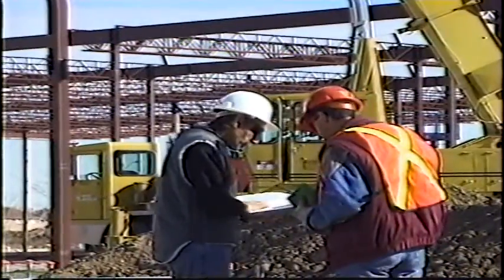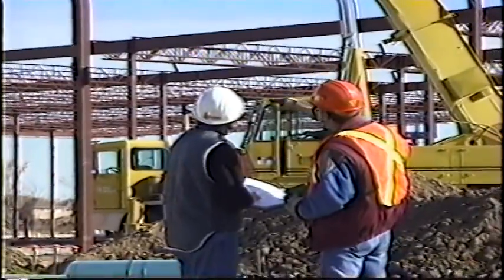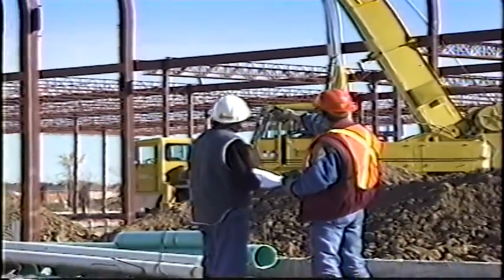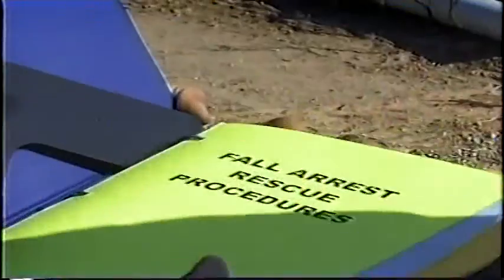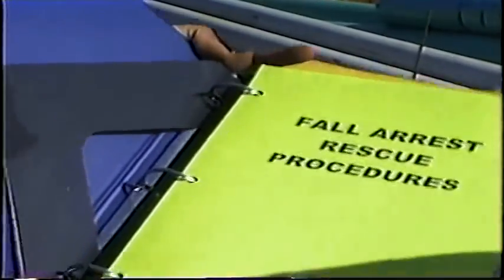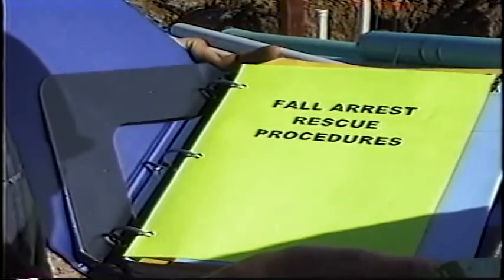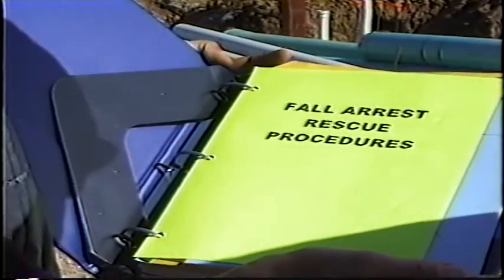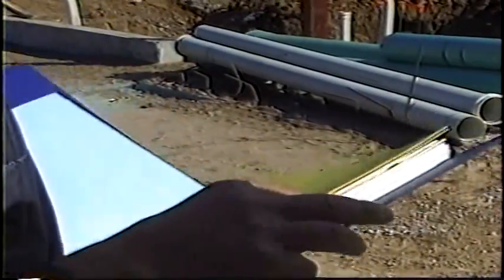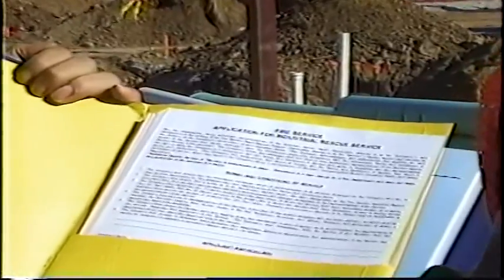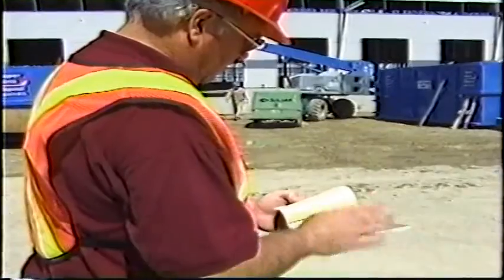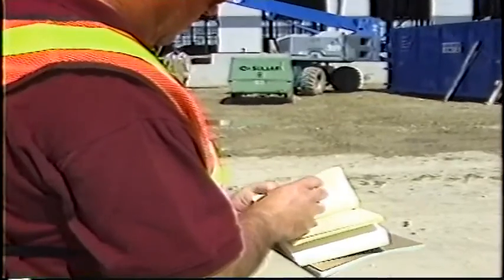Before anyone uses fall arrest systems or safety nets, employers are required to develop written procedures for rescuing a worker in case of a fall arrest. Plans for the rescue of workers who have fallen can vary, from simply pulling them back up onto a safe location, to using a ladder or elevating work platform to get access to them, or in some cases, involving specially trained rescue professionals. Whatever resources are needed, they should be identified and the procedure should be communicated to everyone in the crew. For more information on fall protection planning, refer to your employer's health and safety policy and the construction regulation.